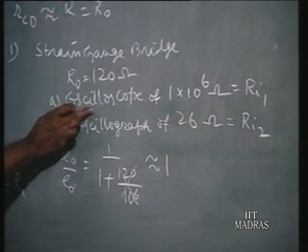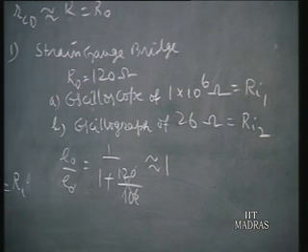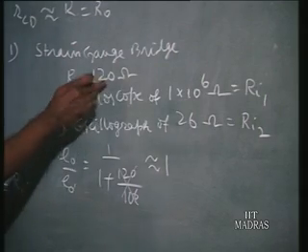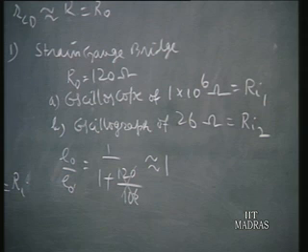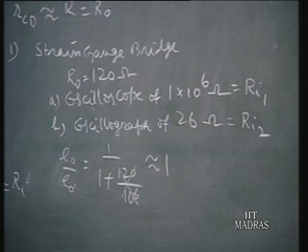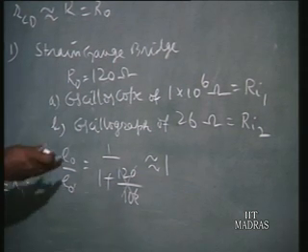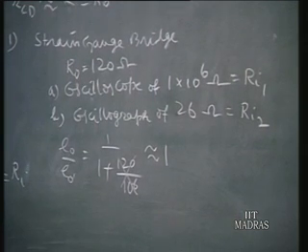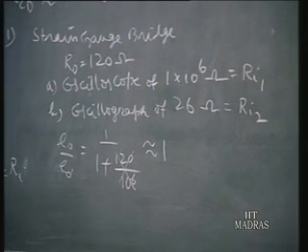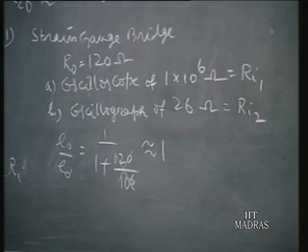So in the case of the oscilloscope, we find the input resistance is much larger than the output resistance, 10 to the power 6 means near about 10 to the power 4 or 10,000 times or somewhere like that. We want only 10 times, it is much more than this. So in such instances we see the loading effect is negligible. That is what is demonstrated here.